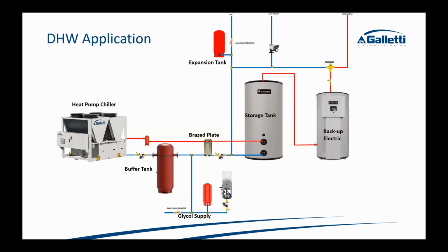A lot of times in the designs, I'll have that second unit in series, the one right before the mixing valve, that backup electric, with a set point maybe 5 to 10 degrees less than the storage tank. So the only time that element's going to be kicking on, for the most part, will be when thermal loss from the tank exceeds that differential. But if you have a big enough differential and you're storing and feeding at a warm enough temperature, you can minimize that pretty well.